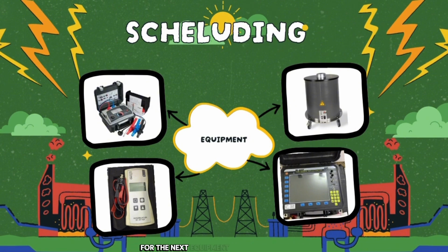The next equipment is high voltage test lead and accessories. Their function is to provide a highly shielded, safely insulated pathway to transmit the high voltage testing signal from our diagnostic card to the cable core without leaking signal or introducing external noise.